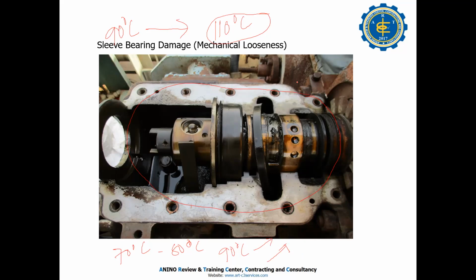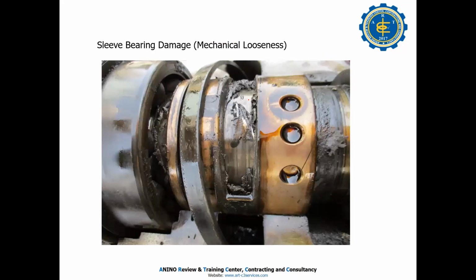Okay, you must monitor first because it's not 100% a mechanical issue. But if vibration goes up and temperature goes up, and then you did not stop, then this is what happens to your bearing housing. See this one?